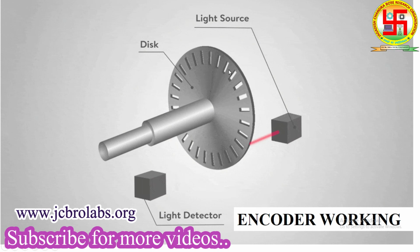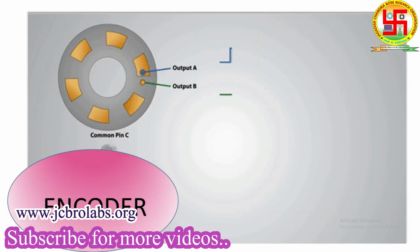The slotted disc has some gaps, and there is a light source, which could be a laser or an LED, and a detector, which could be a photodetector. When a slot comes in front of the light, it falls directly on the detector and it gives high. When there is no light on the detector, it gives 0. This is how the simple working goes, and the same concept can be incorporated in different forms.